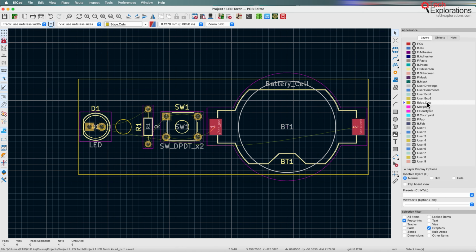I have already designed the outline as a rough outline in this case. I'm going to improve it in a later lecture after I do the wiring. I've got a mounting hole. I can go for more than one mounting hole. So for example, I can have a couple, but I think that one is enough because the PCB will be able to stay in place by matching closely the width of the container in which it will be placed, and with the help of the screw it won't be movable. So one screw is enough.